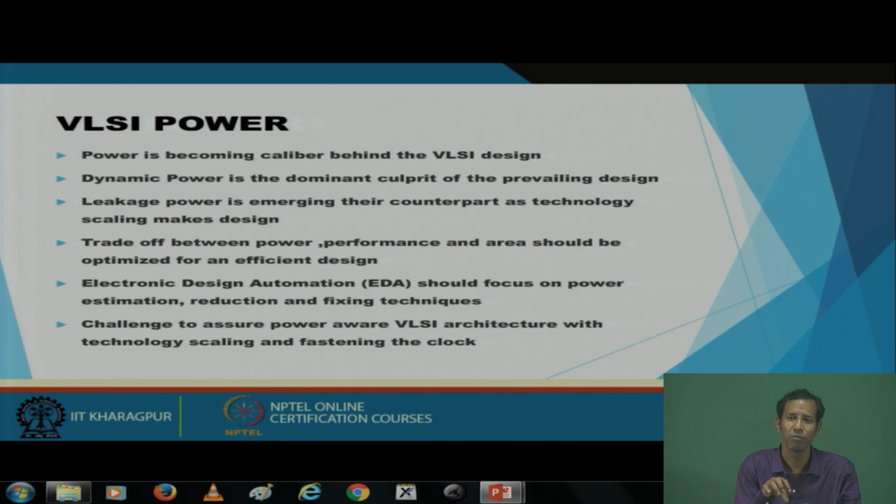in the algorithmic form the EDA tool has already provided it, whenever you do the synthesis. Synthesis means your logic part will be converted into the corresponding gate level. At that time they run the architectural optimization, gate level optimization, and logic level optimization. Every optimization they process and they come up with the optimized expression, which will be represented through gates. That much the EDA tool has developed so far that they can do it automatically.